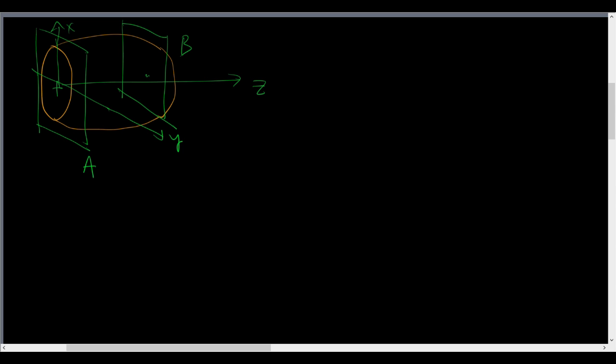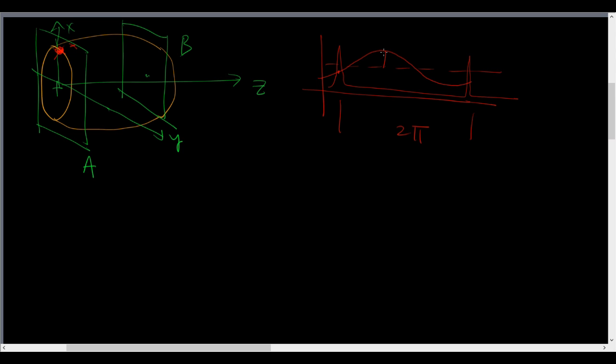What I said was I can put one mass here, measure the change in the vibration. So first I have to put a tracer on this one, so I get some signal. That's my time reference. So this distance is 2 pi. Then without this mass, just the rotor as is has some vibration signal, for which this is one period, so that's 2 pi, that's the average. We'll call that A, and we'll call this distance psi A.